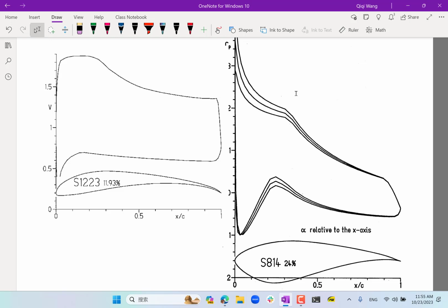The secret of achieving high lift is preventing flow separation over the majority of the airfoil, right? Flow separation over here is fine, but you don't want flow separation over here or over here, okay? And for a laminar boundary layer, when the boundary layer is still relatively thin, you can afford to have a higher adverse pressure gradient. But as the boundary layer becomes thicker and thicker, there are less viscous forces, right? And you cannot afford to have a high adverse pressure gradient anymore. That's why the pressure gradient eases to almost zero along the trailing edge.